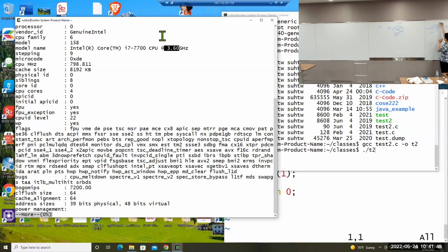And for data, if you execute LDR in ARM, with R0 and R1, you are reading from a memory location. The ALU is doing an addition operation. The CPU supplies R1 and the constant 4, which is an immediate contained in the instruction itself.